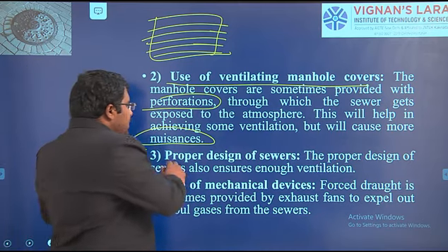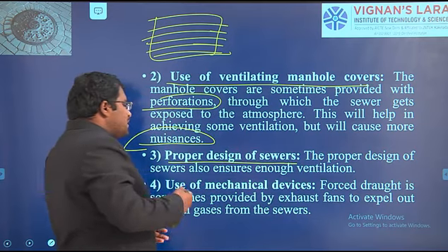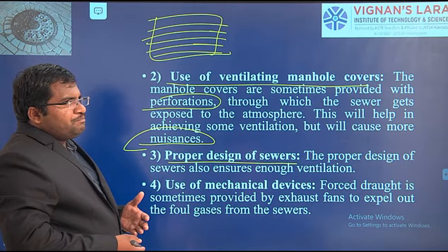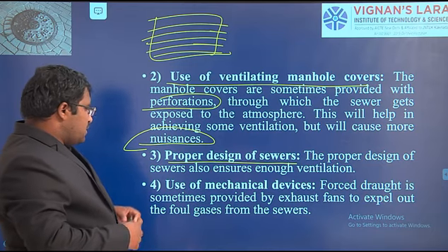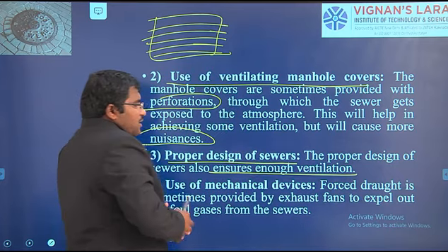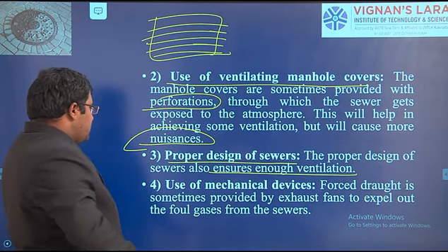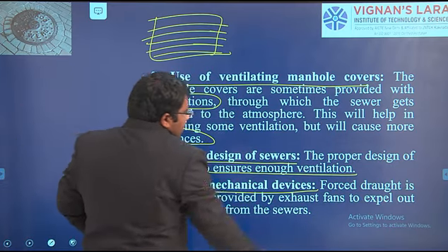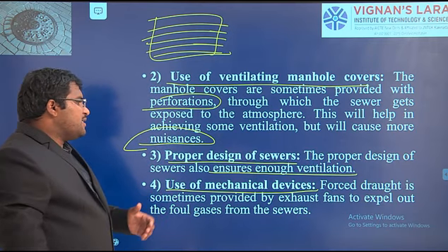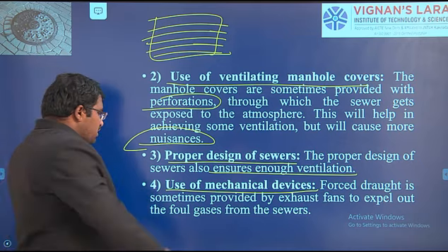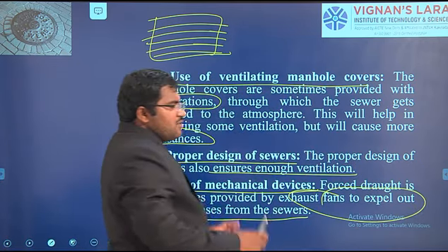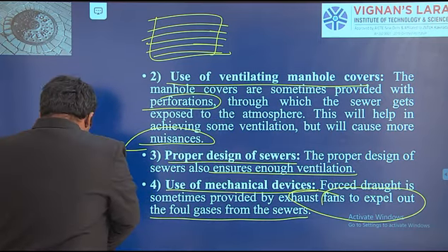Then, proper design of sewers. Sewers should be designed so that there is no accumulation of gases, and they ensure enough ventilation. Then the last thing, use of mechanical devices. Forced draught is sometimes provided by exhaust fans to expel the foul gases from the sewer, so that the gases will move out.